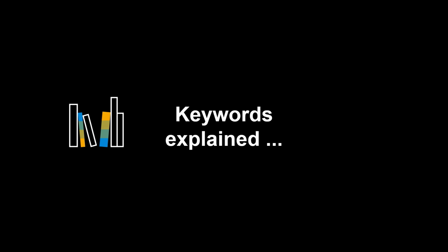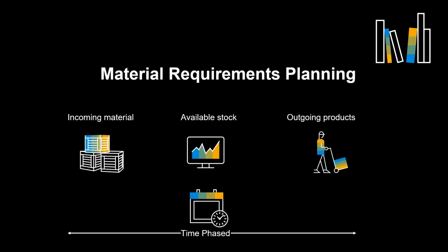Material Requirements Planning, MRP, is a production planning, scheduling, and inventory control system, used to manage manufacturing processes. An MRP system is intended to simultaneously meet three objectives. 1. Ensure that raw materials are available for production, and products are available for delivery to customers. 2. Maintain the lowest possible material and product levels, in store. 3. Planning of manufacturing activities, delivery schedules and purchasing activities.